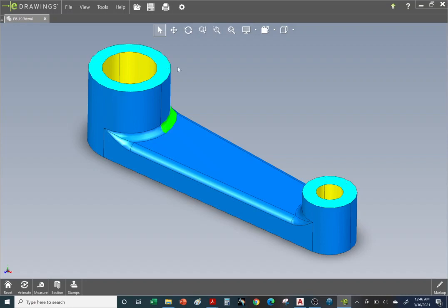So you have a nice, flat, planar surface. So both of these will be parallel, not in the same plane, but they will be parallel to each other, and also in this case parallel to the base, to the bottom, because most likely something needs to attach to these surfaces, or I should say mate up to another part at these surfaces. And same thing with the bottom. Most likely it'll have to mate up with the other part and most likely bolt it together. All right, so let's take a look at the answer key.